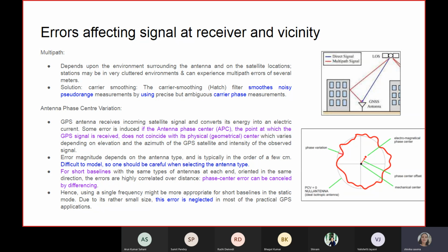Under the same environment, the presence of multipath errors can be verified using a day-to-day correlation of the estimated residuals, because the satellite reflector antenna geometry repeats every sidereal day. Multipath errors in the undifferenced pseudo-range measurements can be identified if dual frequency observations are available. So we have the advantage of using dual frequency. It also helps in removing the ionospheric error. Multipath error is also reduced.